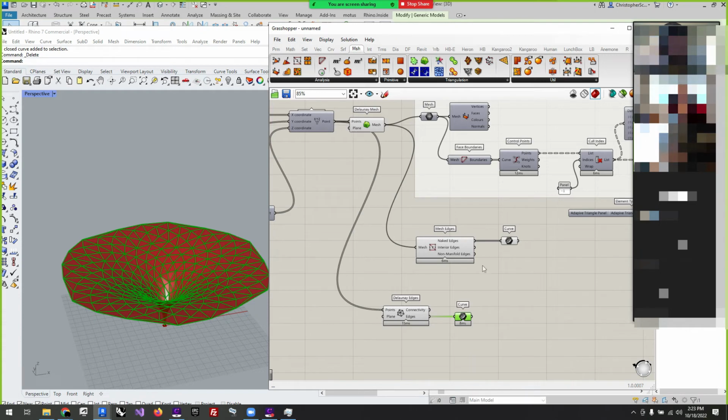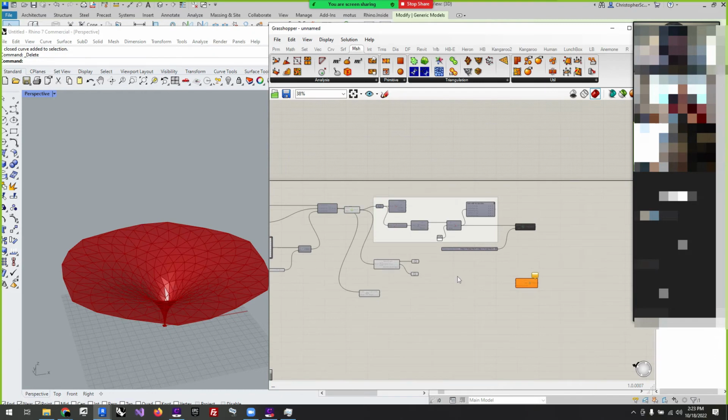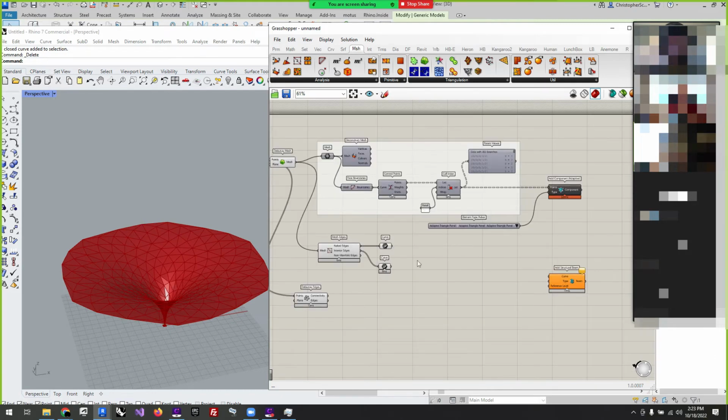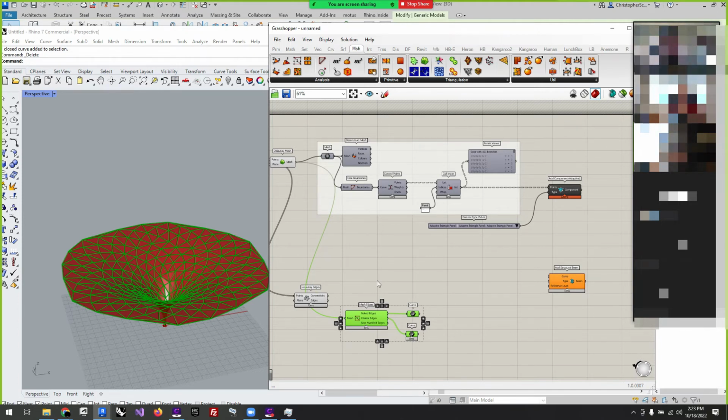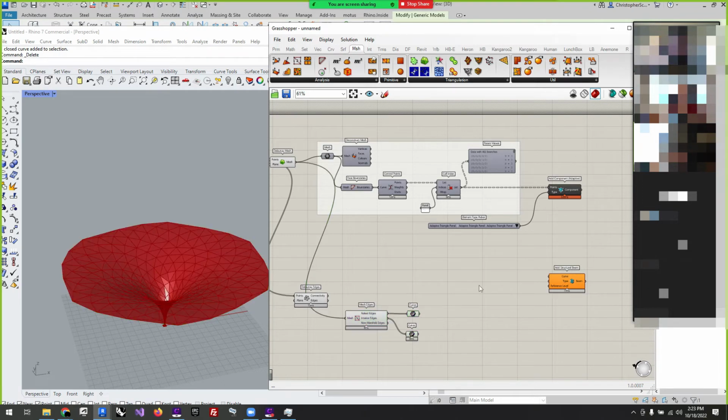Nope, it's also line-like. All right, we're going to see if line-like works. If it doesn't, then we'll go from there. Because I don't believe Revit will allow us to have like a noodly shape for our beams, we'd have to build our own family that then would be our, I don't know, noodle beam or something like that. Revit doesn't do too well with the curves in the inherent beam families.